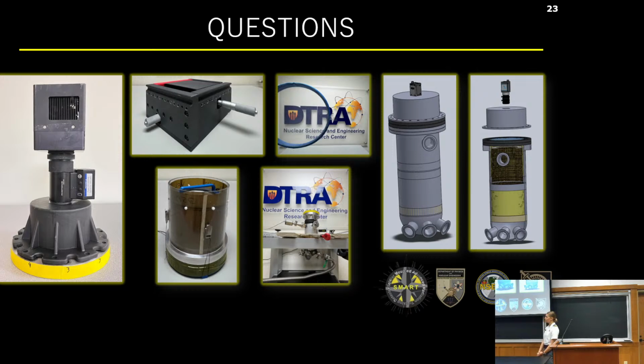As far as manufacturability goes and the reproduction in a mass context or in a repeatable context, the mesh and the ability to emplace the mesh, stretch it, and ensure its continuity is by far the most vulnerable for production and maintenance. If there are any sorts of disruptions on the mesh to include contaminants, dust, things like that, it'll need to be replaced. And over time, it may wear out due to the high voltage that it's held at. So designing the detector in a way that those meshes can be replaced continuously and repeatedly, as well as designing a system that can create them quickly, will be a difficult obstacle.